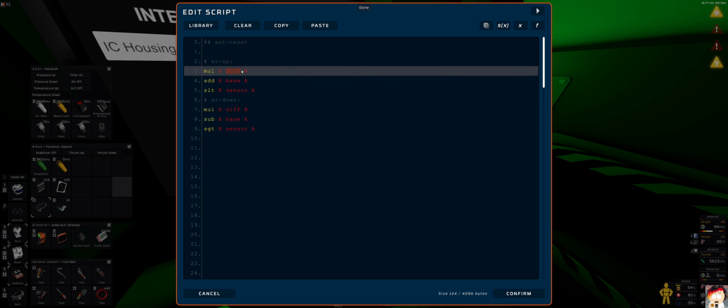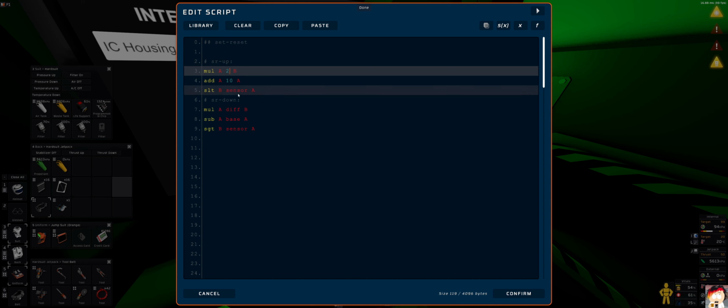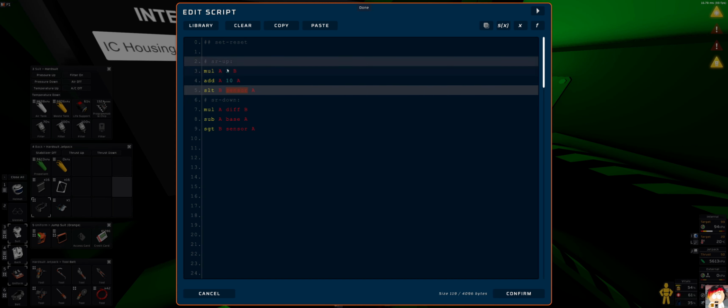And the diff is the difference. So let's say we go on to add something between 10 and 12. We start adding when we go below 10, pushing up to 12. So this will be our number 10, and this will be 2, right? So what it means is if we are at a sensor value of 14, this will return 0. If it drops to 13, it's still 0. It drops to 12, still 0.